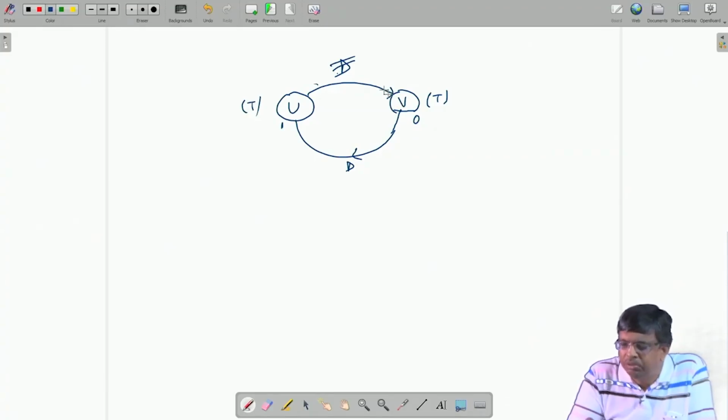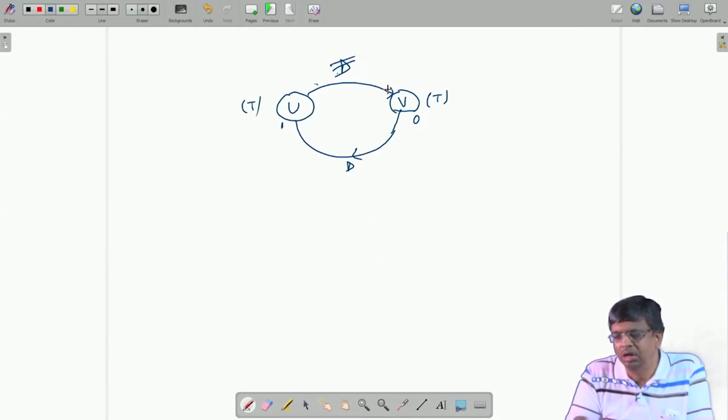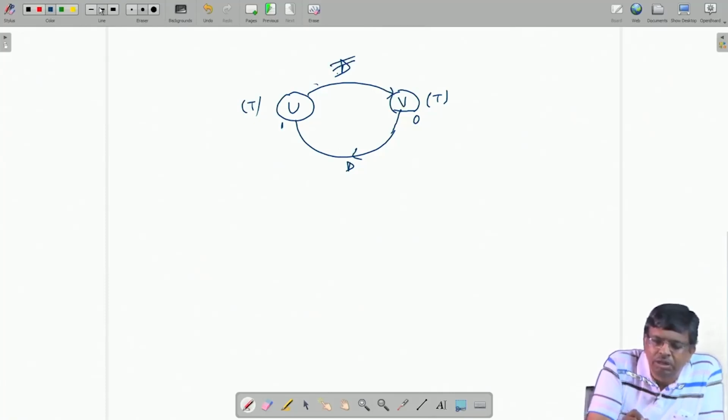But upper half no delay. So, in one half you first take time t, do this job, in the same cycle give it here, it takes another time t. So, t plus t, 2t. So, critical path remains 2t. Delay only has come down from upper half edge to the lower edge. So, it does not help me, the retiming here does not help me in reducing critical path at all. Okay. But you see there will be a change now.